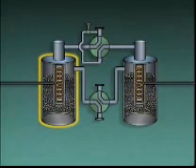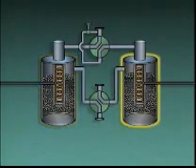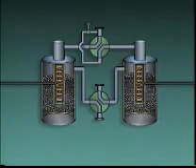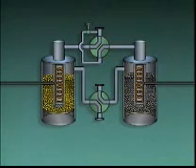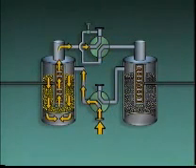An active tank contains dry desiccant that is used to remove moisture from compressed gas. In the other tank, desiccant is being dried or regenerated. In this example, the dryer is set up so that each tank can either be an active tank or a regeneration tank, depending on the positions of the four-way valves. The desiccant in the active tank removes moisture from the gas that flows through it. Most of the dry gas leaves the dryer through the gas outlet.